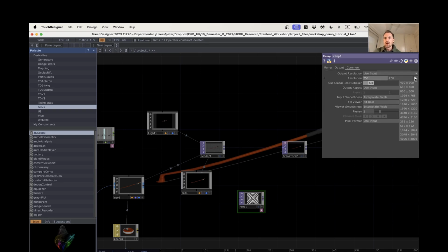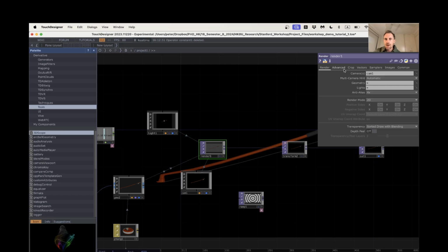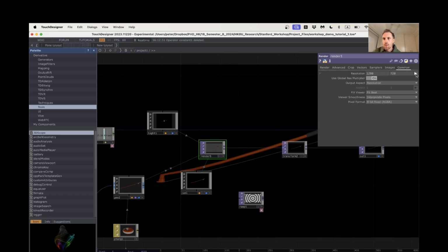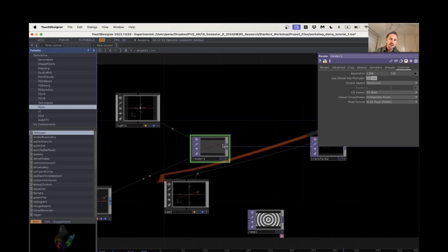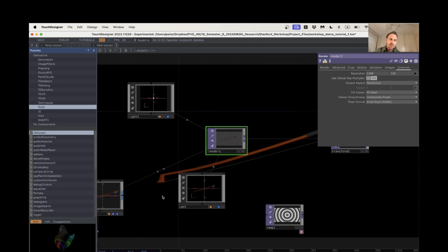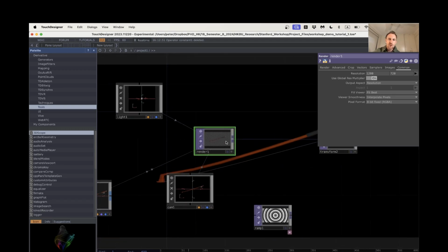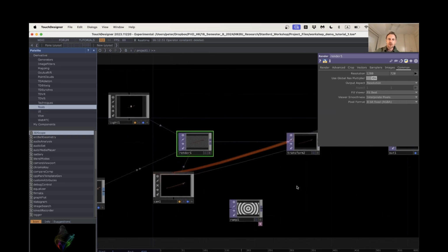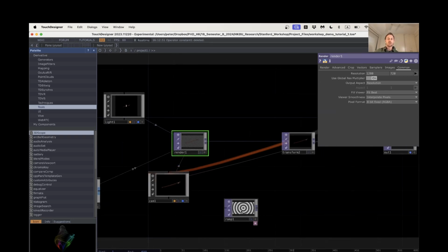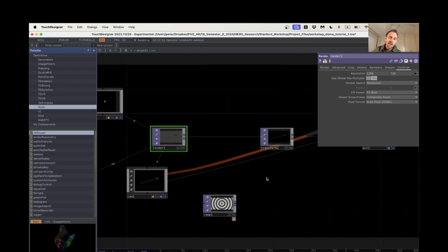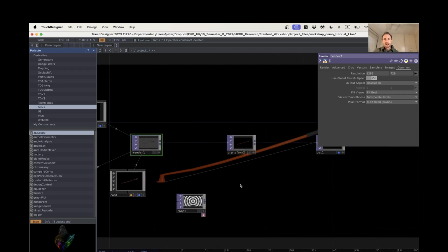If you're using the free version of TouchDesigner, you're limited to a resolution of 1280 by 720. So I'll set that there, and check in our render that we're rendering the same, 1280 by 720. That's saying that whatever 2D image our camera is rendering, now we're in 2D space with this pixel dimension. And if we want to composite these in a way that is logical, it's good to have them at the same resolution.